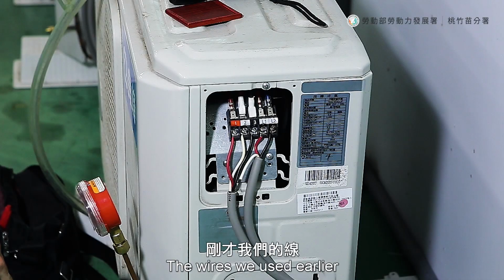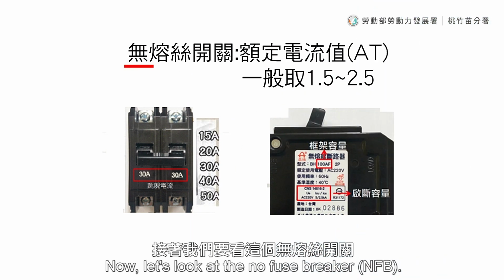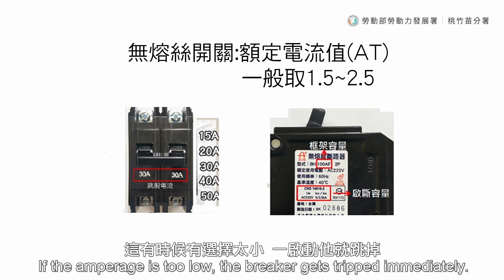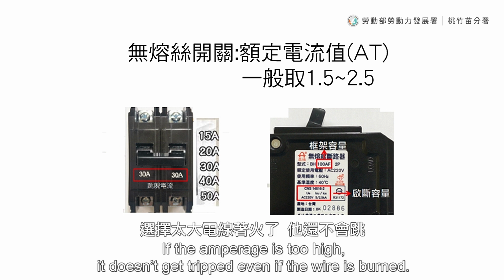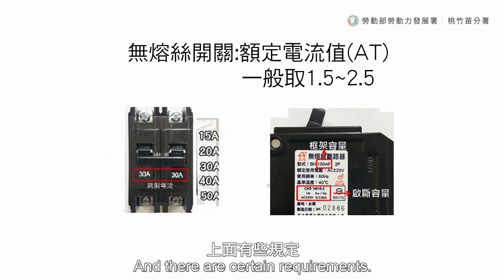The wires we used earlier are connected based on color or numbering. Now let's look at the no fuse breaker. If the amperage is too low, the breaker gets tripped immediately. If the amperage is too high, it doesn't get tripped even if the wire is burnt. There are regulations for this, and there are certain requirements.